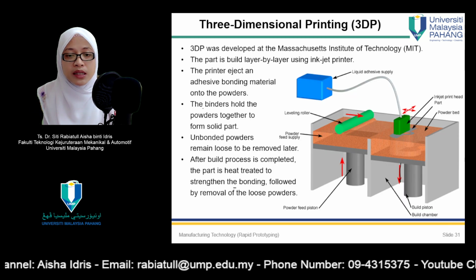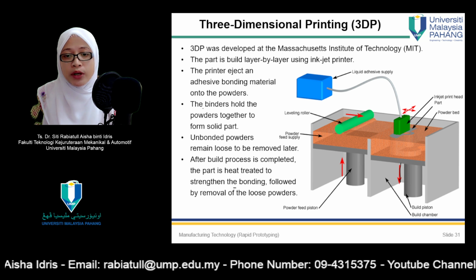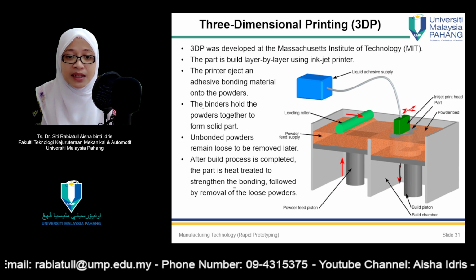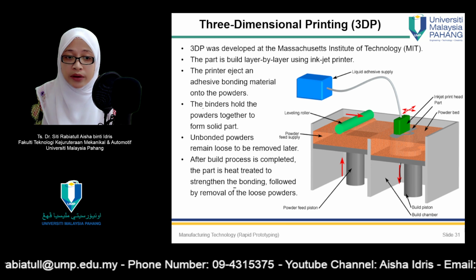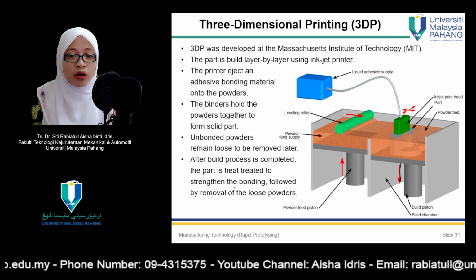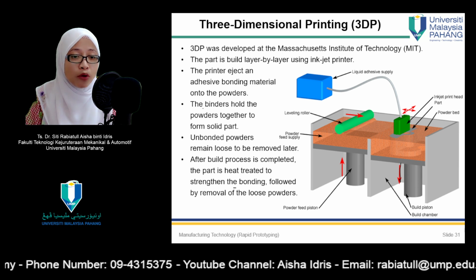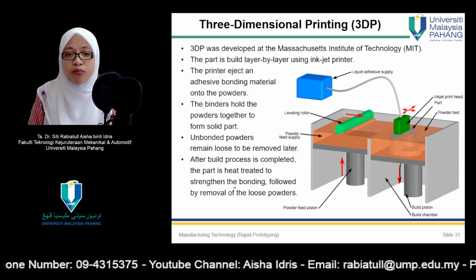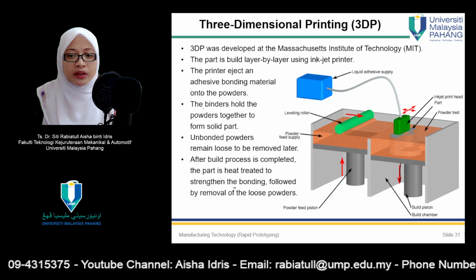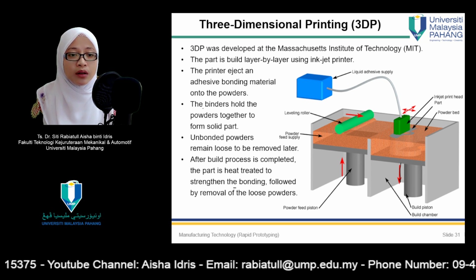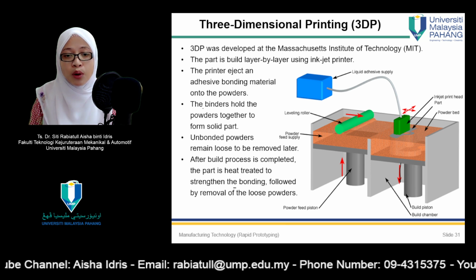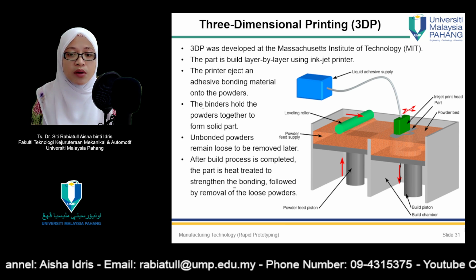The binder is deposited in areas corresponding to the cross sections of the solid part as determined by slicing the CAD geometry model into layers. The binder holds the powders together to form the solid part while the unbonded powders remain loose to be removed. While the loose powders are in place during the build process, they provide support for overhanging and fragile features of the part.